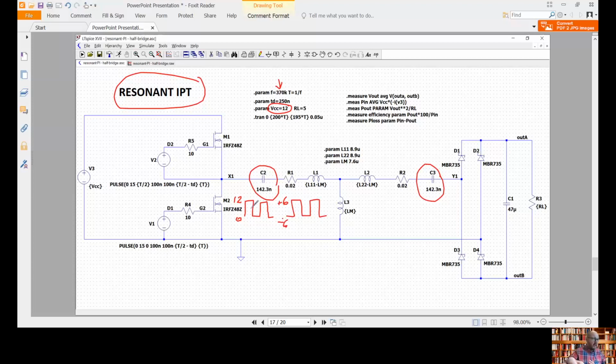So at the end, what we have to consider that we inject into our system is the first harmonic of this waveform, because the other harmonics are going to be filtered. If we calculate the amplitude of this waveform, it is going to be something like 4 times 6 divided by π.